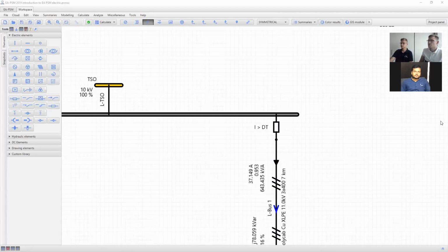How many nodes do I need to evaluate an impact of connecting renewable sources to existing grid of a small town? So technically, it depends how far the solar power plant is from the main transformer substation. If it's very near or even directly connected to bus bars in the substation, so technically you do not need to specify the whole town network.